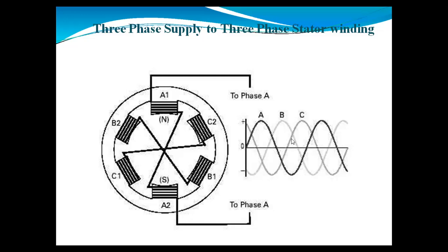So here we can say we are giving the three phase supply by using the R Y B phase sequence, in which we are giving all these three phases the equal magnitude of voltage. And if you see the two adjacent phases, the phase angle of voltage between two adjacent phases will be 120 degree.